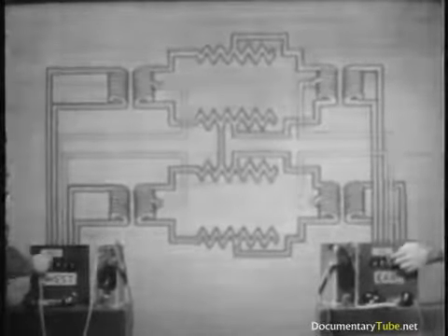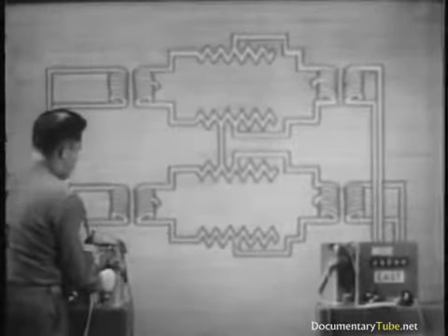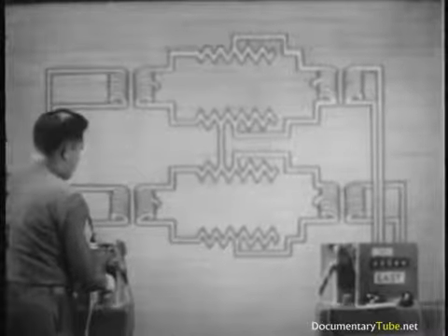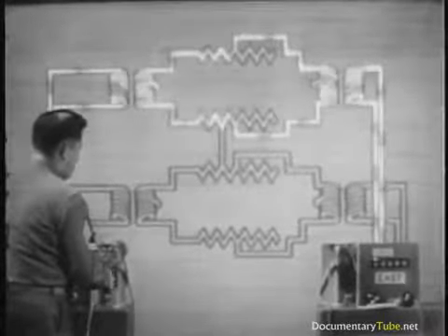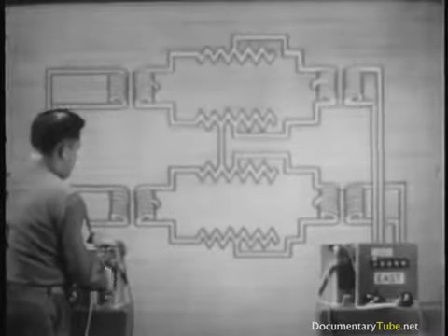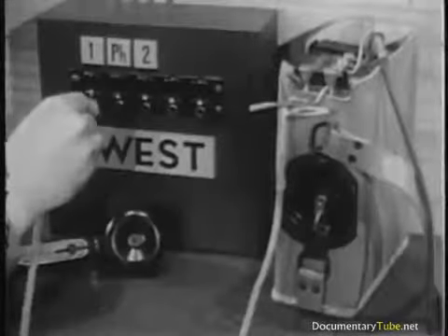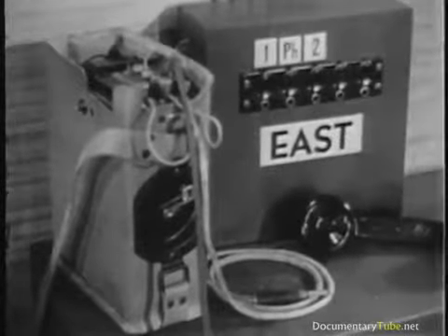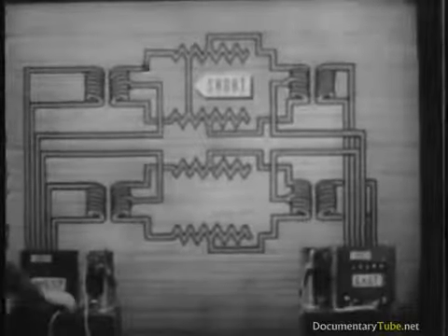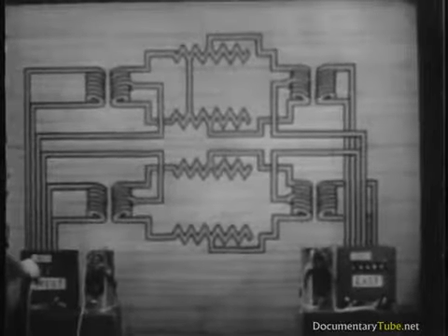If we cut out the phantom connections at both ends, the 2 side circuits can be used. Actually, we no longer have a phantom group. What we do have is 2 metallic circuits accidentally crossed, and we won't get any more interference between them than is usually caused by this condition. A short on a side circuit affects only that circuit.